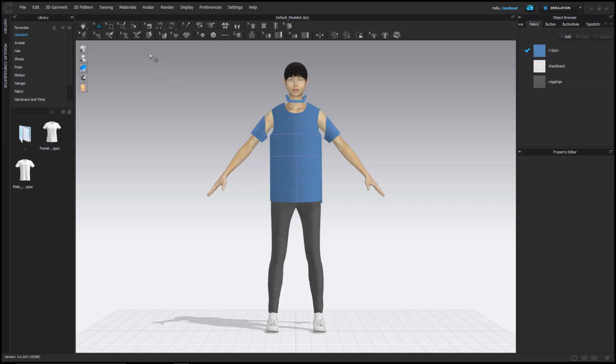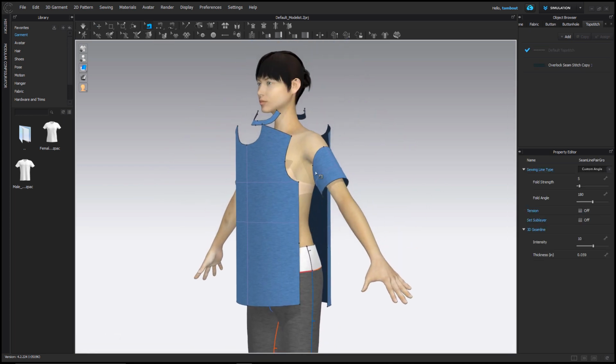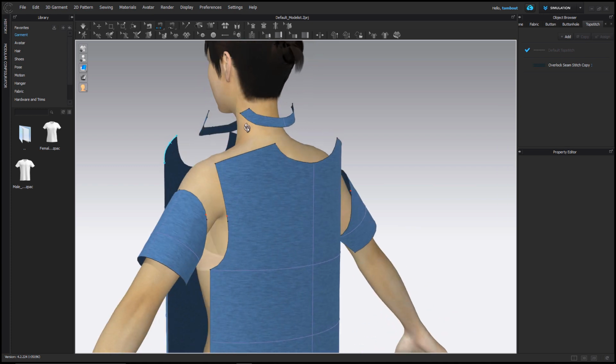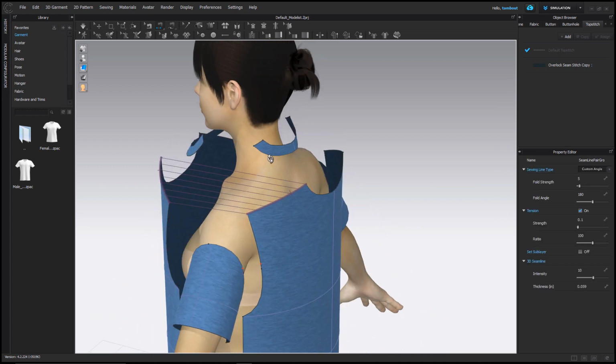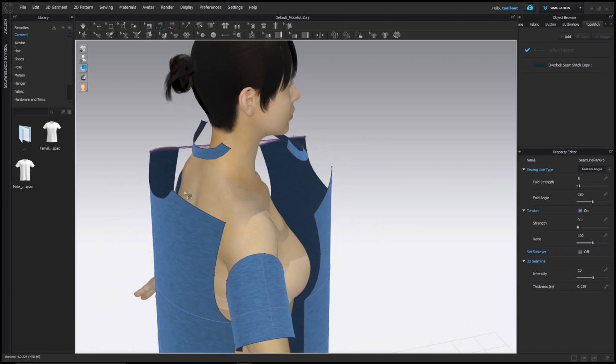As of CLO 4.2 release, you can now edit sewing in the 3D window. Use the Edit Sewing tool to view, select, and edit sewing arrangements. Use segment sewing to sew two segments together. Simply left-click on two segments and match notches to create a sewing arrangement. If the sewing arrangement is properly sewn, the sewing lines that appear will be straight, connecting the two sides.